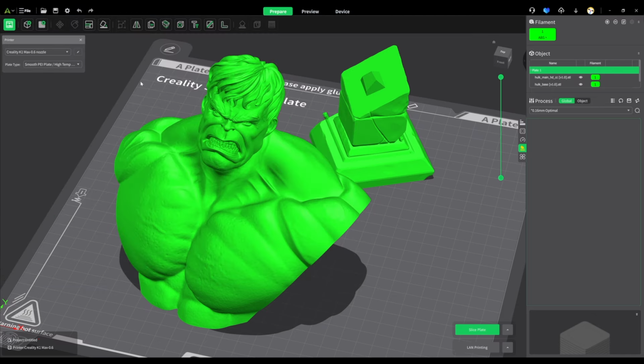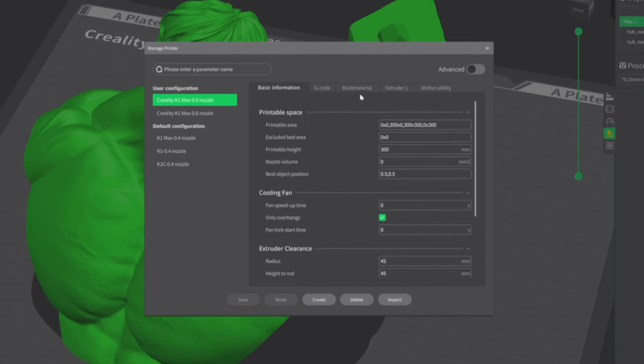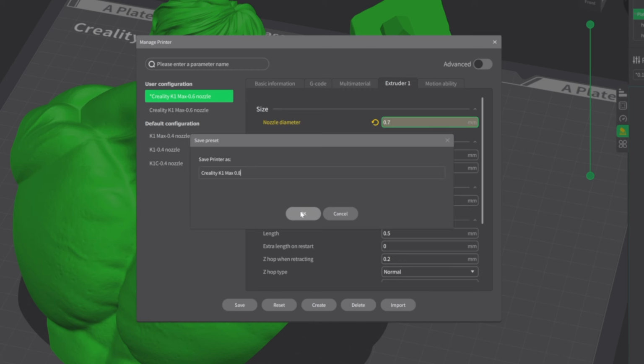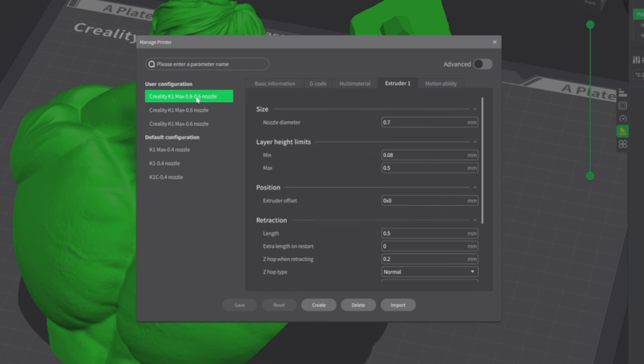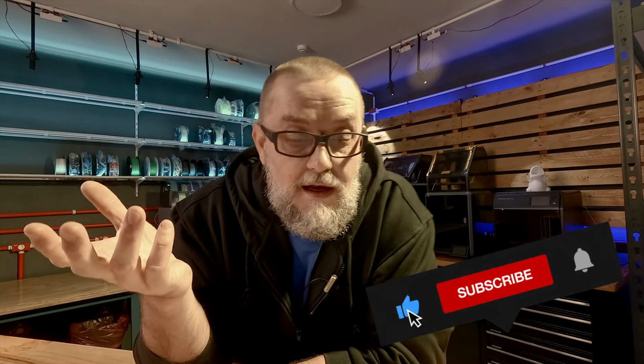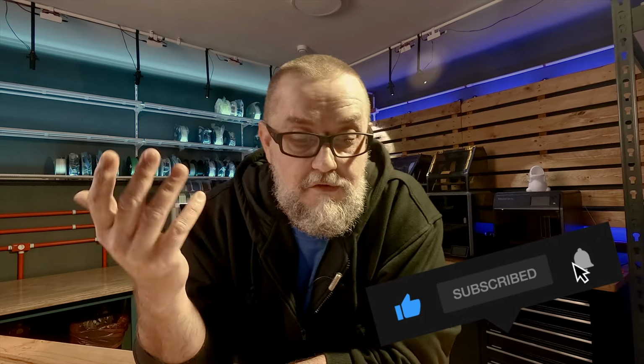And then when I tried to rename that or create a copy, trying to force the Creality Print slicer to understand that I'm trying to save a 0.8 millimeters profile, Creality Print slicer simply doesn't care. I tried to rename, I tried to duplicate, and it's still saving that profile, thinking that the nozzle size is 0.6. So beyond the fact that they are not publishing profiles for different nozzles and different printers, the software is making the job of importing from other software difficult. So this is a bug that must be fixed as soon as possible.